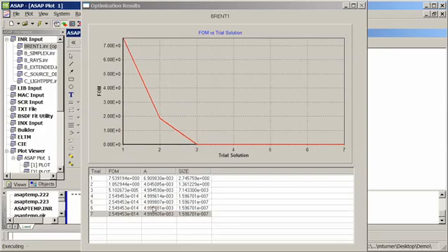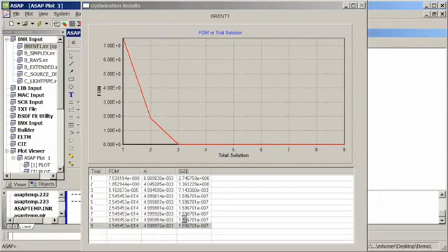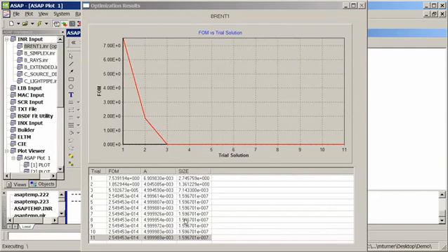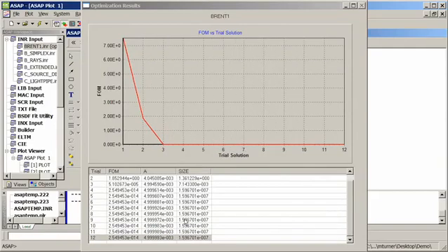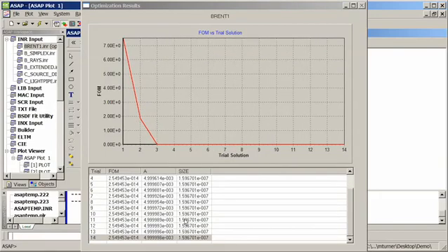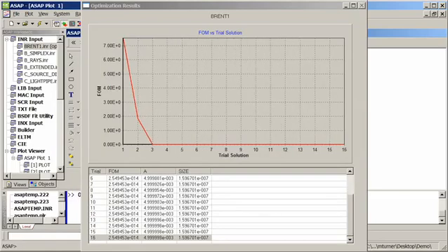And as you can see, in a very small number of cycles, we've probably reached the optimal solution where the RMS spot size is effectively 0. ASAP will iterate through this several cycles, and then when it determines, based on the repeatability of the measurement, that it's not changing, it will cancel out of the measurement. As it's done at this point, it's decided that this is the optimal value.